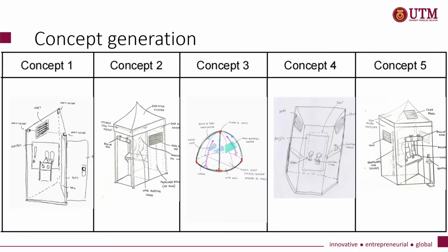The third design is hemisphere-shaped, nylon cloth as wall material, normal zip as entrance type, and vinyl sheet as window material. The fourth design utilized pressure-molded plastic sheets for the wall material, a normal door for entrance type, wraparound rubber gloves for sleeves mechanism, double vents ventilation, nuts, bolts, and rivets for fasteners, and clear acrylic for window material. The fifth and final design is intended to use Oxford polyester for wall material, roll-up door and Velcro entrance type, also wraparound rubber gloves as sleeves mechanism, normal vents, and clear acrylic as window material.